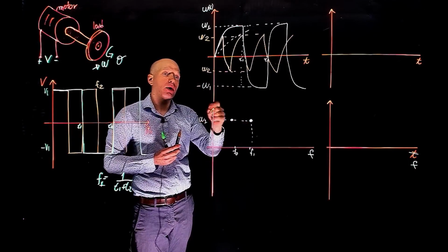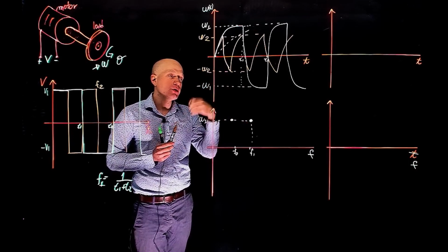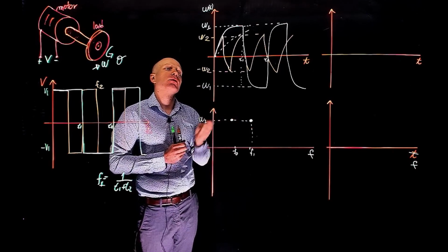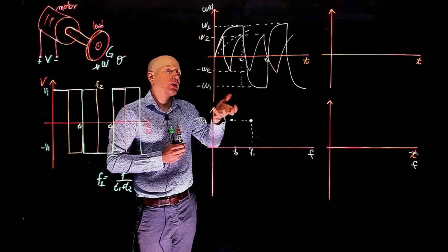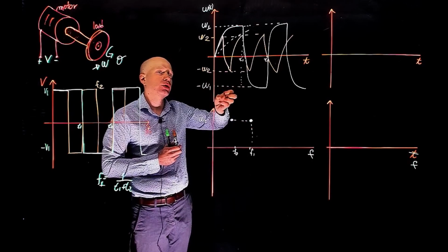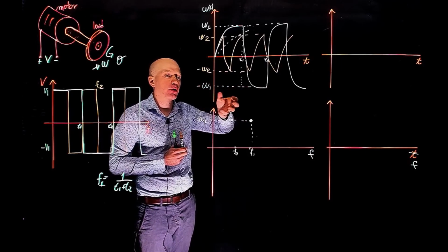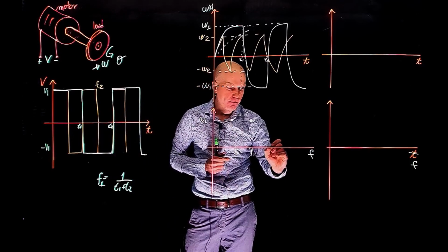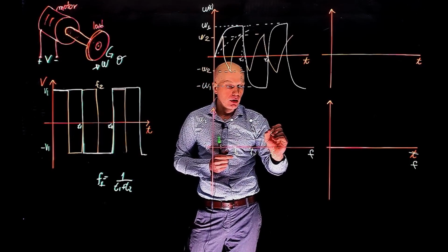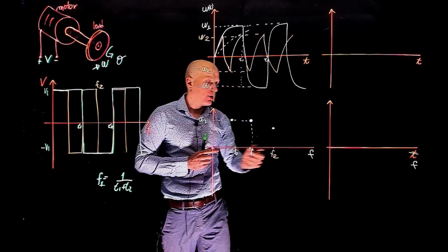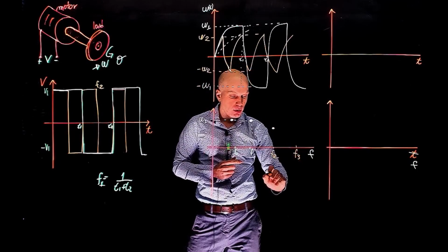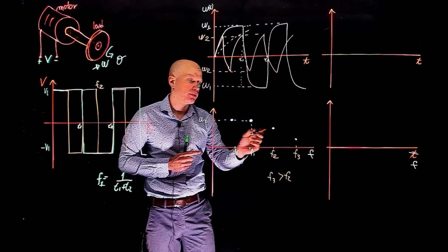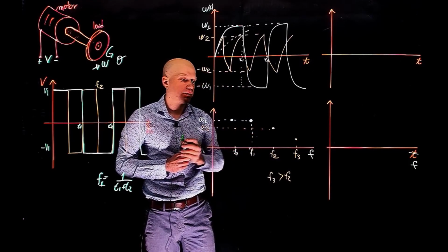Clearly, omega 2 is smaller than omega 1 because we are giving the system less time to develop a speed, and that time is not sufficient for the motor to reach its full speed. We are now going back and forth. So the motor, of course, the less time we give for it, the higher the frequency, the lower the maximum speed we reach. So now if you go at frequency F2, we will see that will start to decrease. And if you go now to a frequency F3, where F3 is greater than F2, that will further decrease. Here we have our omega 2.